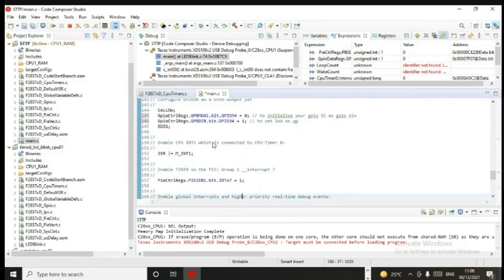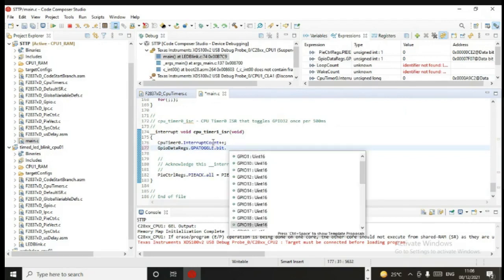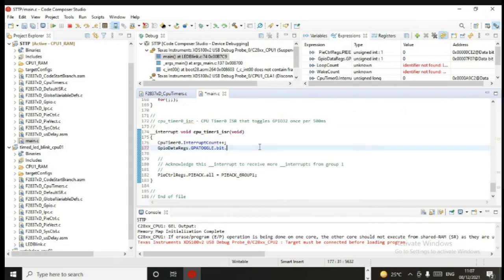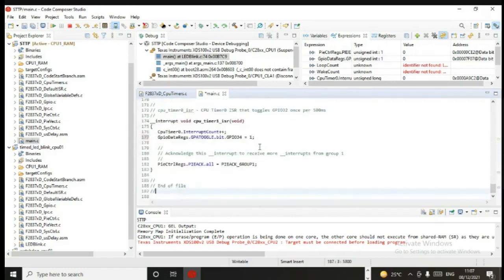Yeah, it's related to B. If you are unaware of this, you can just erase this, click here, and you can see whatever GPIOs are related to this particular thing will come over here. If it is not coming in blue, it means it is wrong, so you have to put B here. If it comes in blue, it means this instruction is correct now.